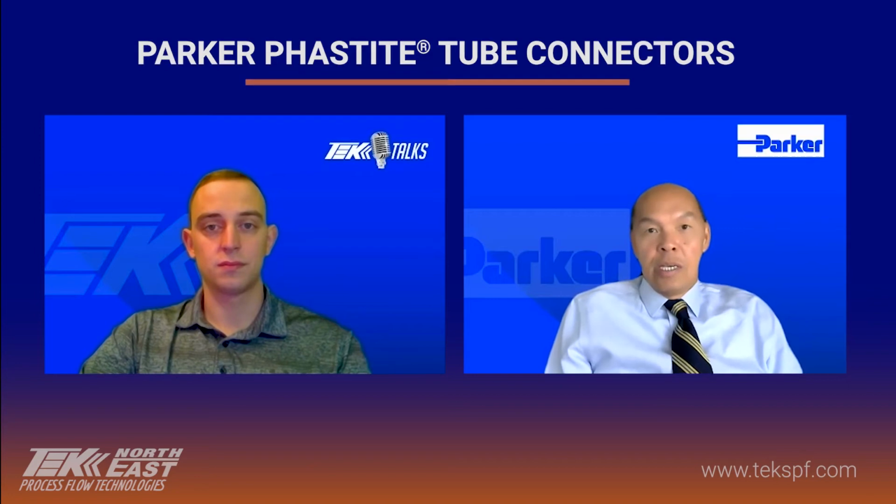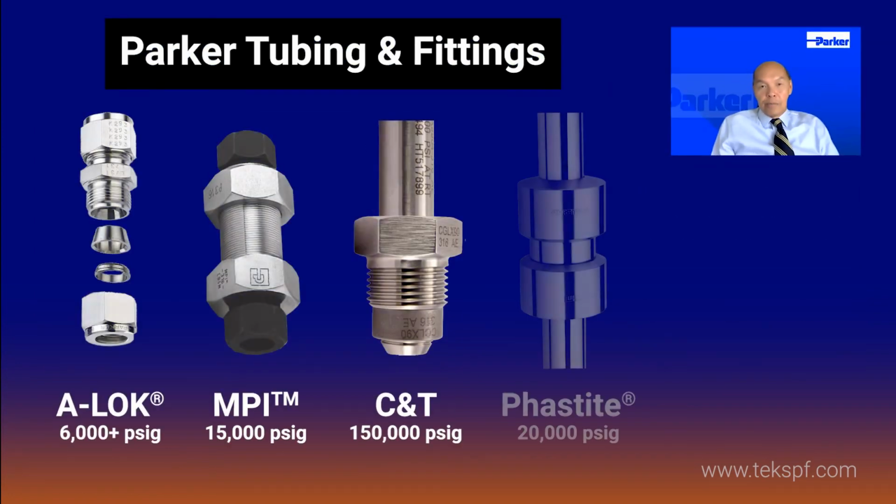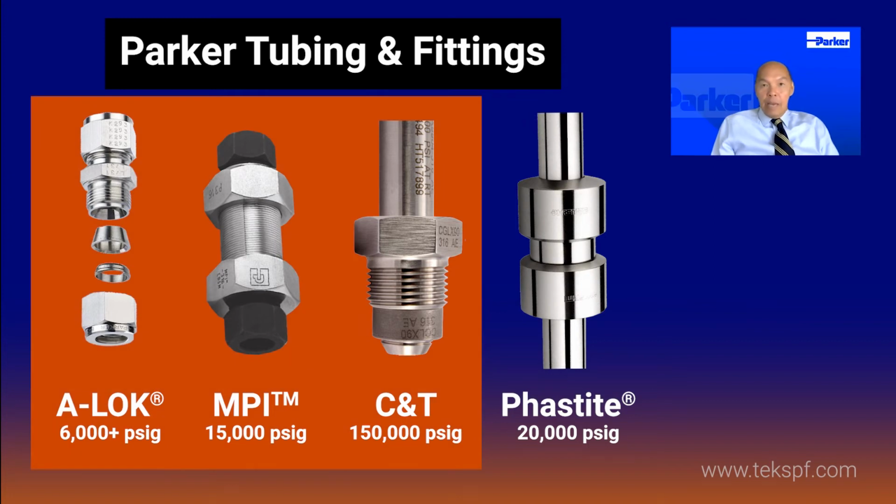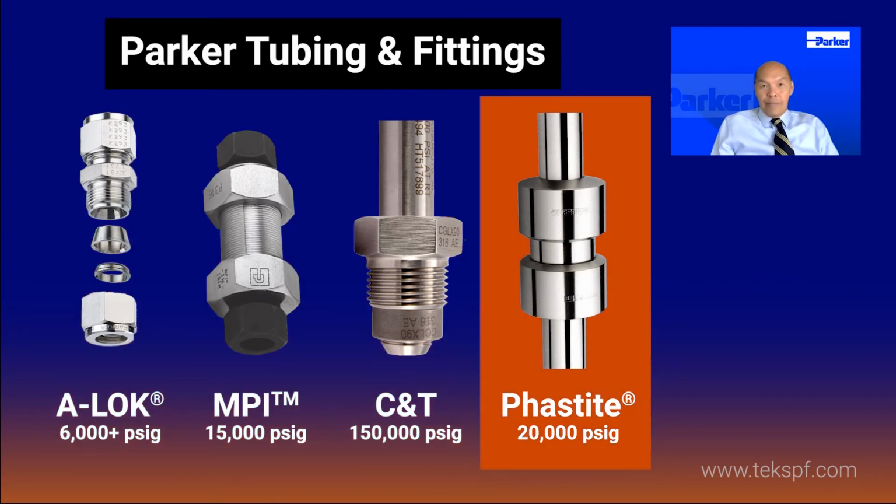You'll see on this slide there are 4 fittings, and the first 3, the A-Lok, the MPI, and the CNT, which is cone and thread, are all threaded fittings, so you have to loosen the nut and thread it onto the body. Whereas Phastite is a fitting that does not require any threading and is a permanent weldless connector.